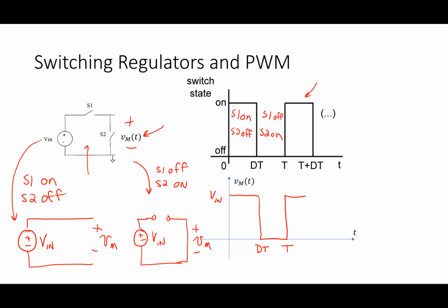You're not used to thinking of something like that where I got switches. What would it be? Well, first of all, what's the Thevenin equivalent circuit looking into any terminals? Voltage source and a resistor, or voltage source and an impedance. What's the voltage source looking into V sub M? It's a voltage source that looks exactly like that figure I drew, right? And what's the resistance? Should be 0 if I've just got switches here, right?